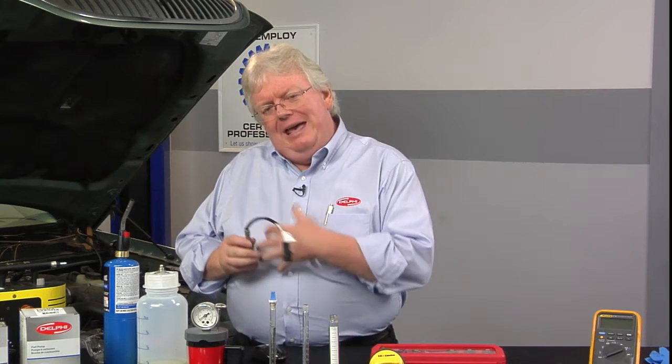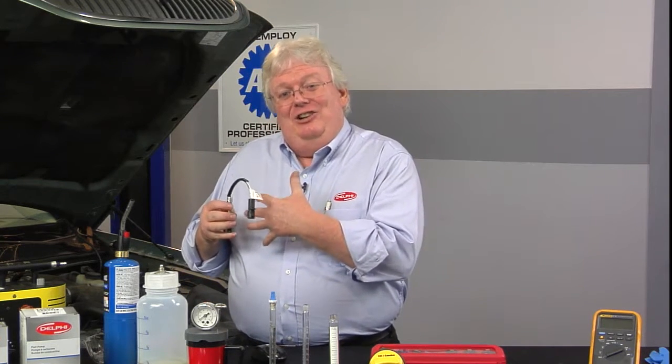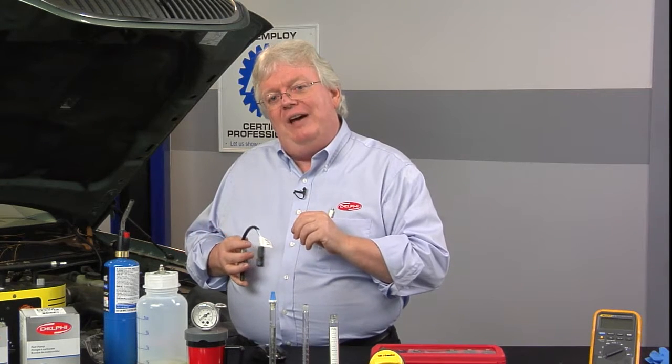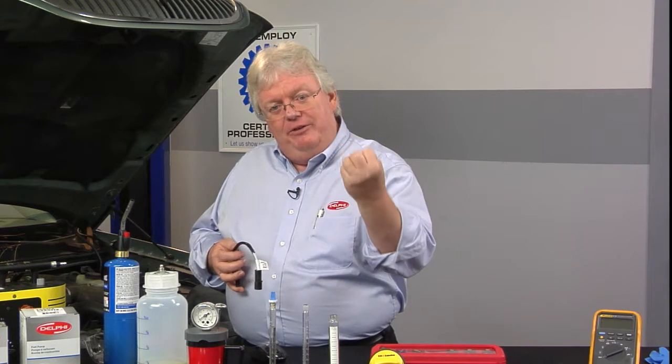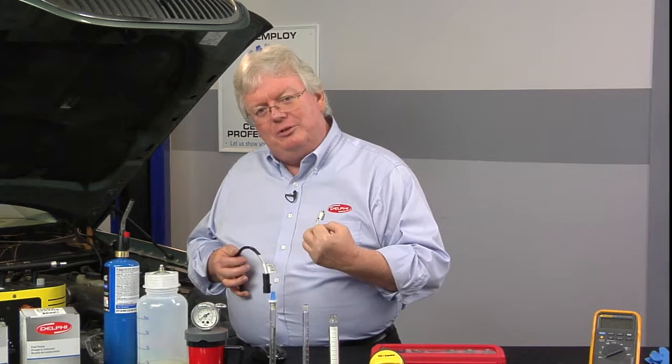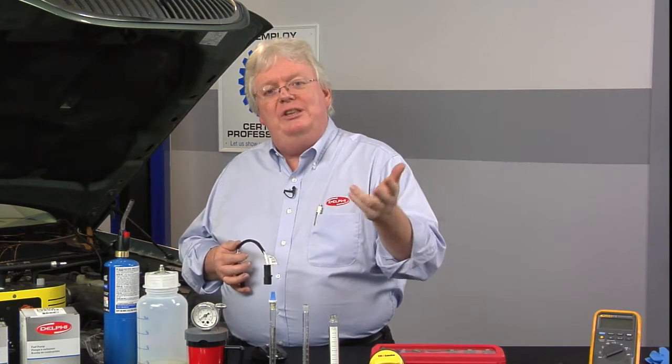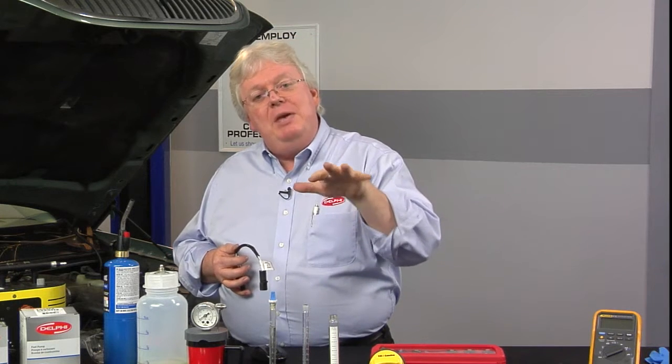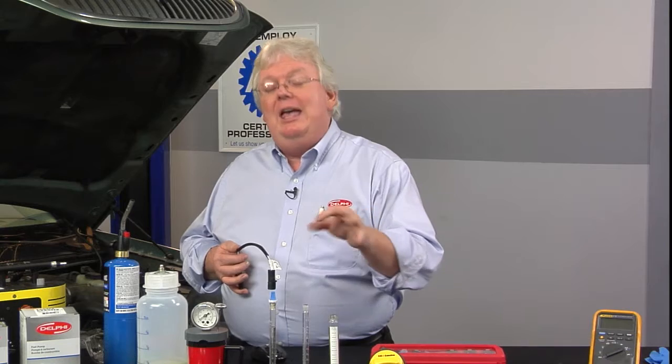Rear fuel trim takes into consideration a little bit of variation in how the engine management air-fuel can be driven by the rear O2 sensor. Now, in most conditions on vehicles that do use this value, it is very minimal. Under certain conditions, like degraded front O2 sensors, rear fuel trim can be very profound.